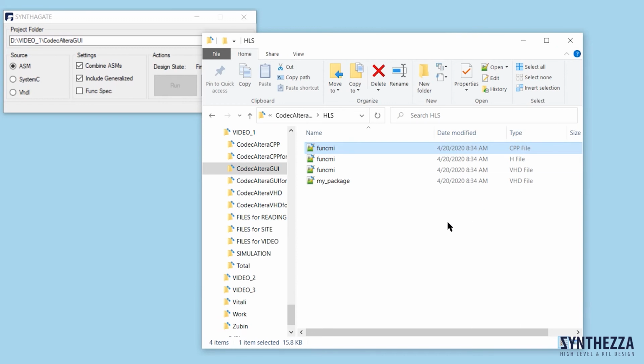After preparing a test bench, the designer can simulate the functional project with any simulation tool. The designer must choose what we would like to use in the simulation at the high level, version in VHDL or version in SystemC. The same test bench can be used at the last stage of design, at the RTL level. I will return to this simulation a bit later. Now let's look at the RTL design.